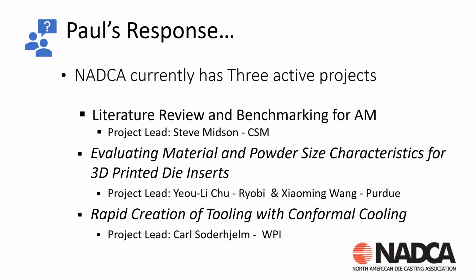And we have determined that if you've got any kind of large powder, 45 micron or larger, you're actually going to have defects that are going to form in the printed materials. So you want to maintain a smaller particle size when you're using powders for printing inserts.